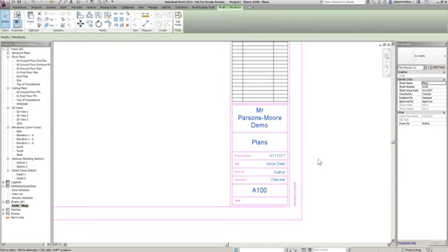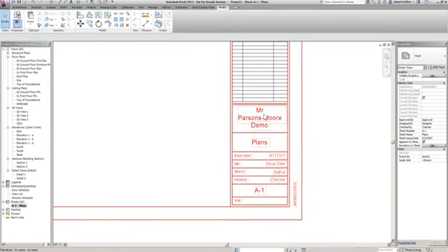A1111, whatever it's going to be. Okay, issue date. It's all pretty obvious. I'm going to call this A1 for my first drawing sheet. Okay, just look down here. It will call it by the drawing number and the drawing name. This information here and my project number is what we call project specific information. Every drawing sheet that has those labels on them will have that same information on there. All of the rest are drawing specific, sheet specific.